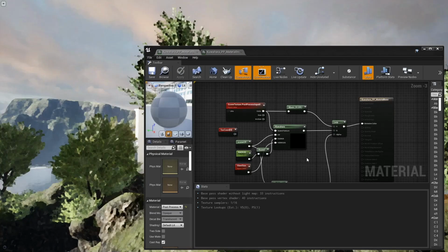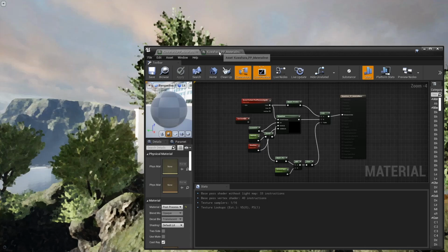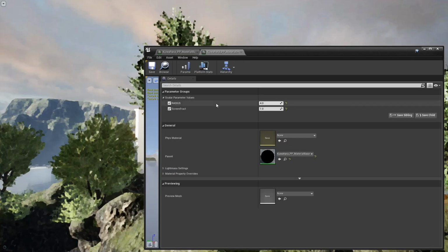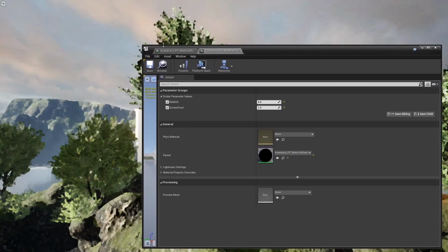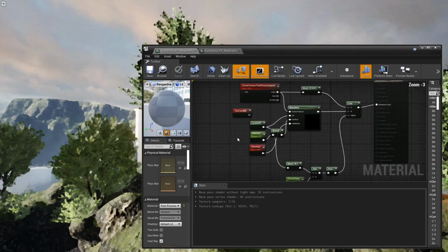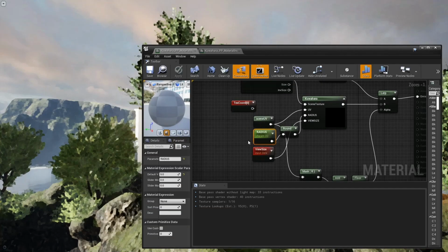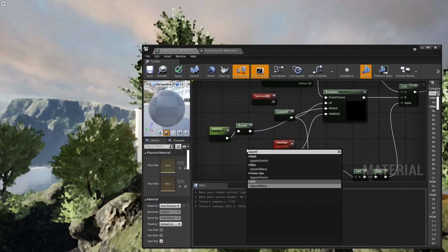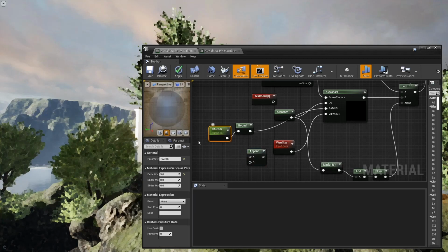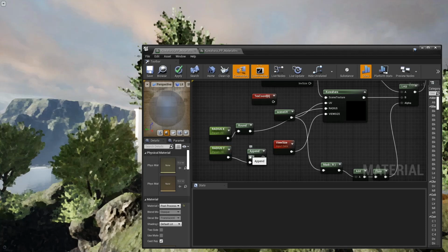So to make the material anisotropic, we're starting from the same base. The settings that you're currently seeing here are still almost identical to the previous video, but we want to split this radius parameter into a separate x and a y. So what we'll start with is we'll add an append node, rename this to radius x, create a radius y, append these two together, round that, and plug that in.